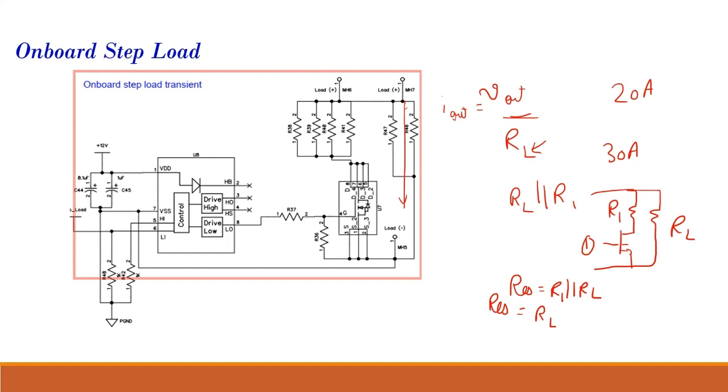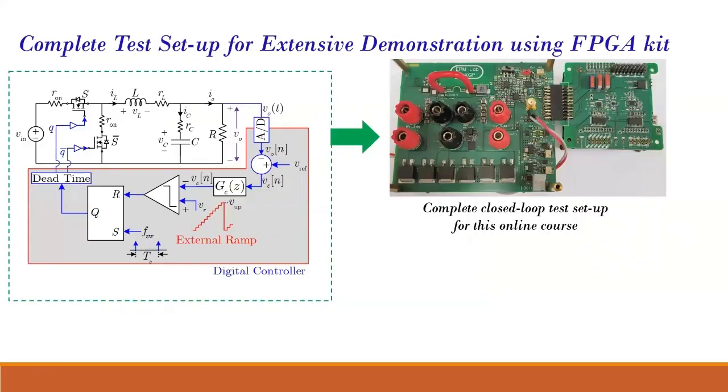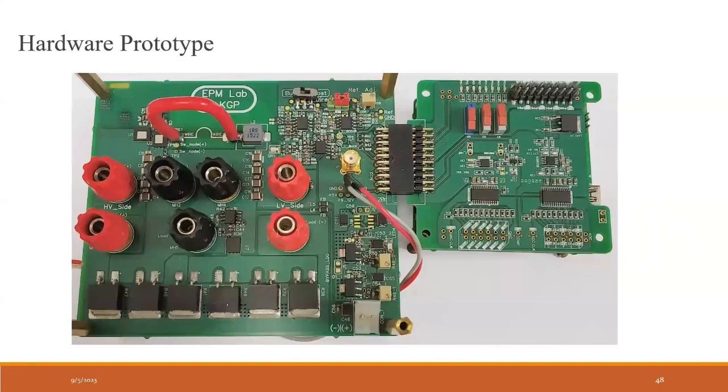Sir, similarly in the current measurement in the previous slide, the PCB, before the red color wire which we use, to measure this current, if you want to see this in the DSO, we want to use that differential probe measurement.